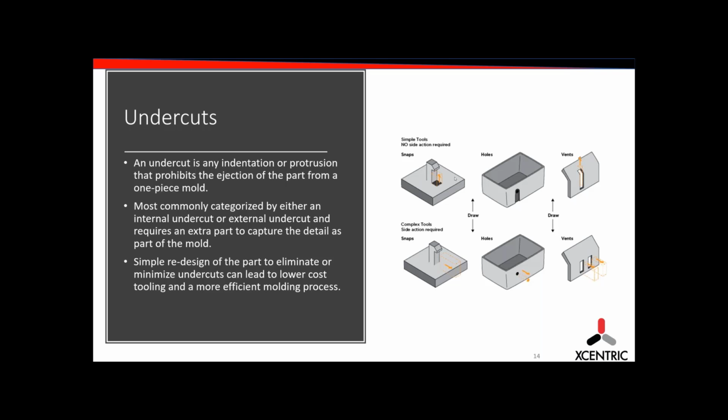Okay, just a couple more questions. What are the major design changes needed for a part designed for 3D printing that now I want to create for injection molding? One of the biggest challenges I see with a 3D printed part going to injection molding is making sure you don't have any voids in the part, undercuts, and that your nominal wall thickness is uniform. A lot of 3D printed parts are layer-based, and you don't have the challenges of high pressure, high heat